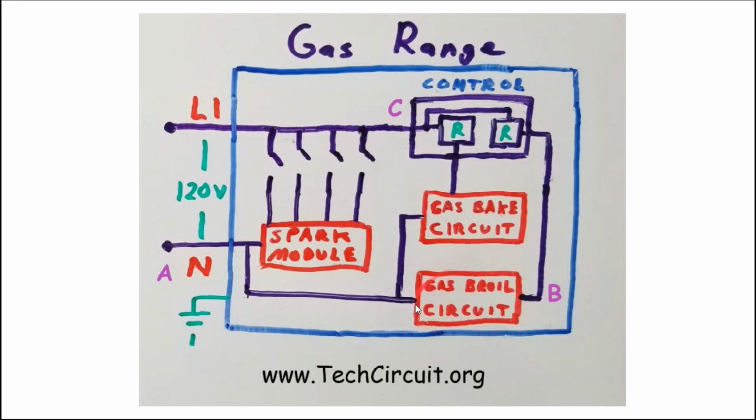And again, this will have the highest resistance in the circuit because this is 0 ohms over here. This is supposed to be 0 ohms. And you're going to have some resistance here. The highest resistance wins, and it's going to have all the voltage across it because it is a single element in the circuit and of the highest resistance.